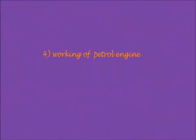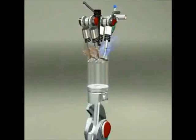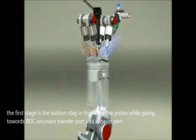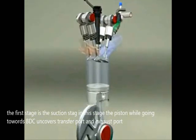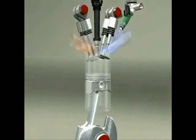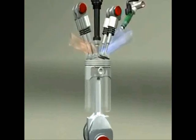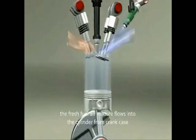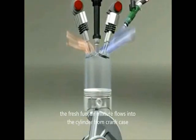Working of the petrol engine. The first stage is the suction stage. In this stage, the piston, while going down towards BDC, uncovers both the transfer port and the exhaust port. The fresh fuel-air mixture flows into the engine cylinder from the crankcase.